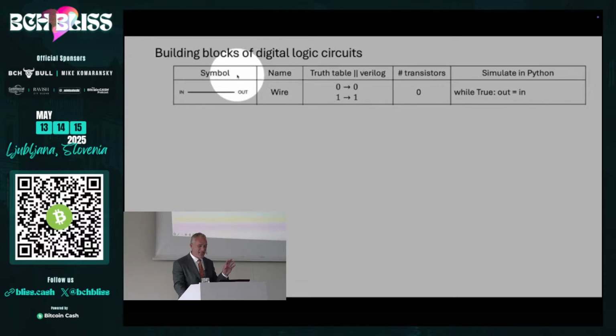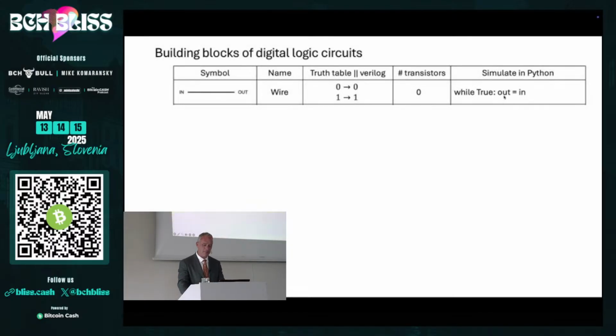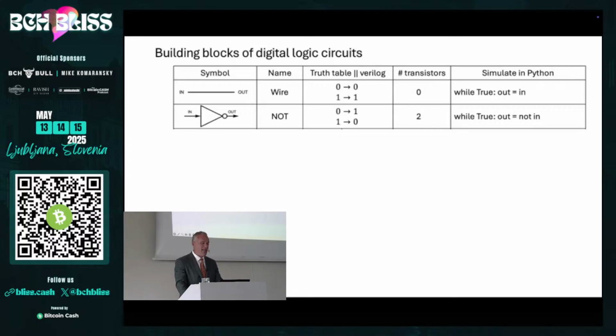Now this actually stumps some of the software guys. So they might say that with a lot of work, maybe it could be as fast as 1 clock cycle. But that's totally wrong. It takes no work at all, and the signal propagates at the speed of light because it's literally just a wire. And this is one of the reasons hardware can be so fast, is you get this built-in while loop for free. And this is a NOT gate.